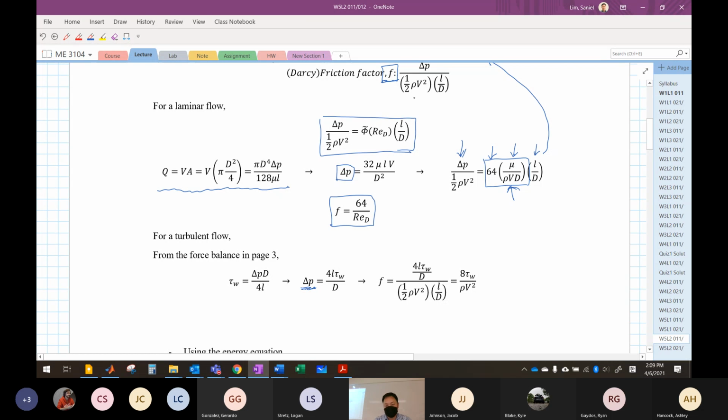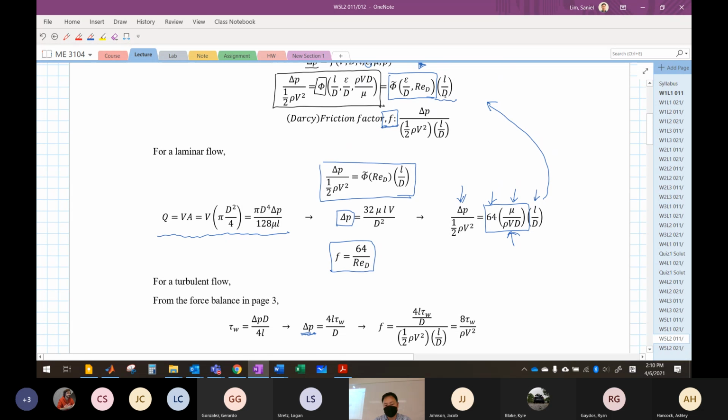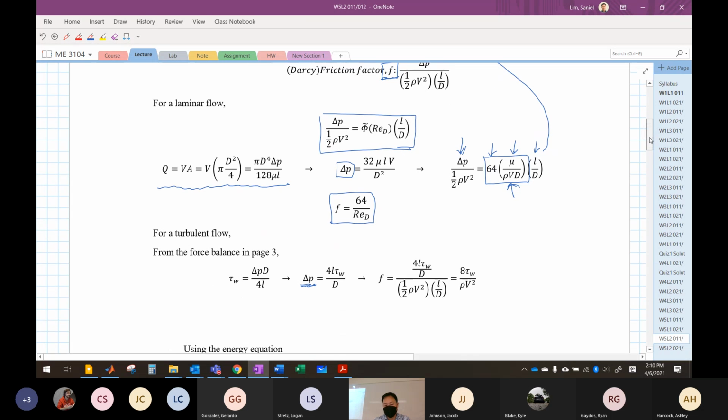All right, what we did was try to fit this equation into the dimensional analysis, which means we can divide the whole thing by the dynamic pressure, right? Then what we have is we can define the friction factor for the turbulent flow. That can be expressed in this term: wall shear stress over rho v squared. All right, what can you find here? Yep, nothing here.